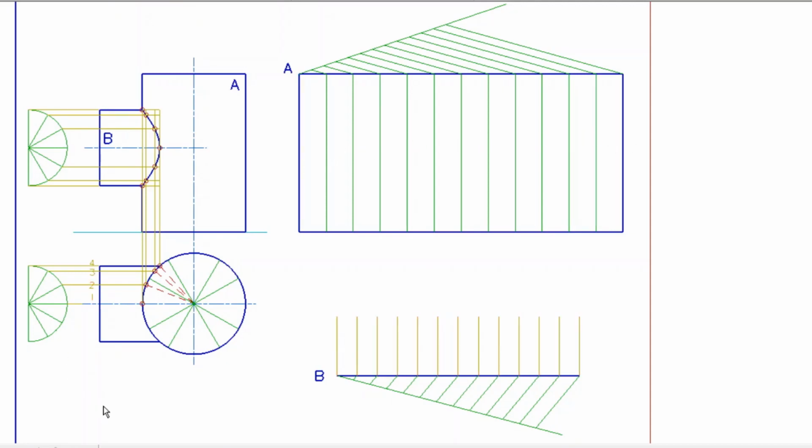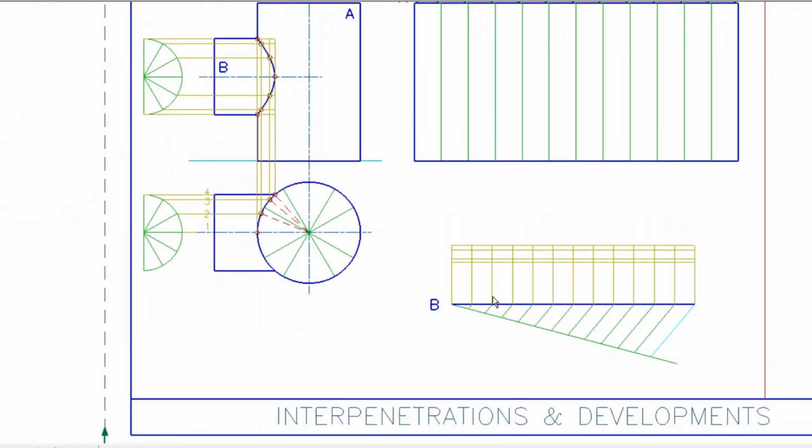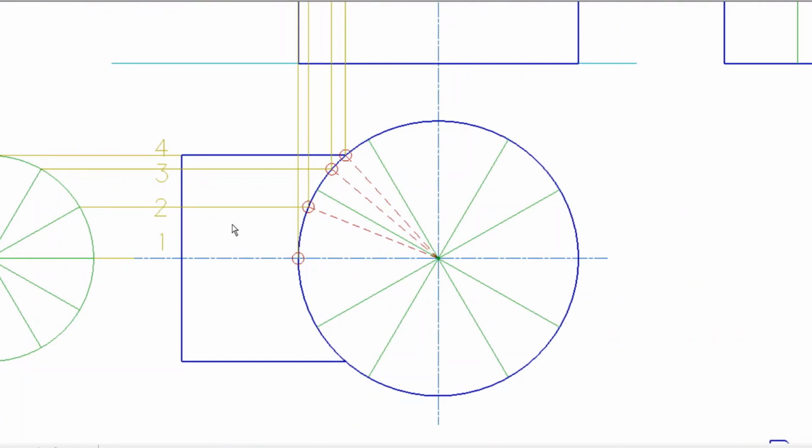So I'm going to do the branch first. Step 1, you're going to take each point and just draw a construction line up. You don't know how high, just draw it high enough. And then you'll see that I've actually marked down these horizontal lines going across the profile. So where do I get that from? Well, if you go to the top view, all the lengths here are true lengths. For example, obviously I'm only doing half because it's symmetrical. So for example, here's the first line.